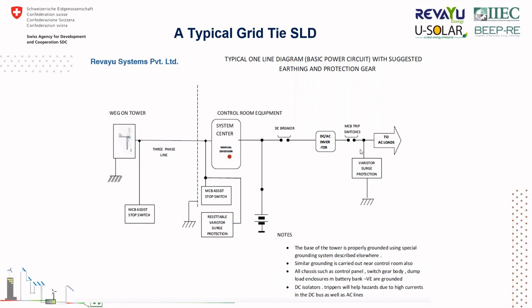And then, if for any reason people want to switch off, there has to be an MCCB in between before the final termination, from where we can disconnect the wind turbine when we require. Even for maintenance purposes, sometimes we need to disconnect. So there is an MCCB to disconnect the system from the normal supply mode.